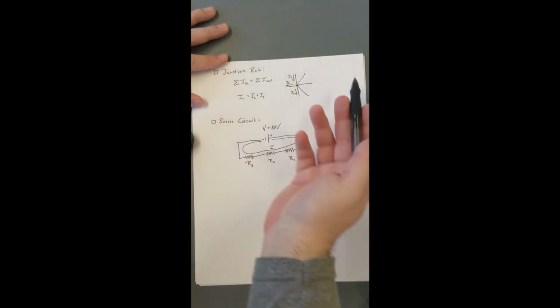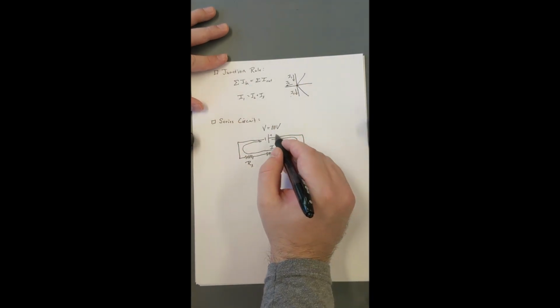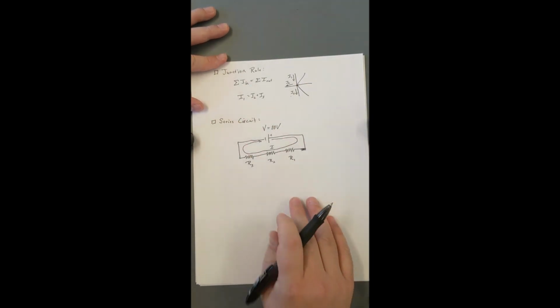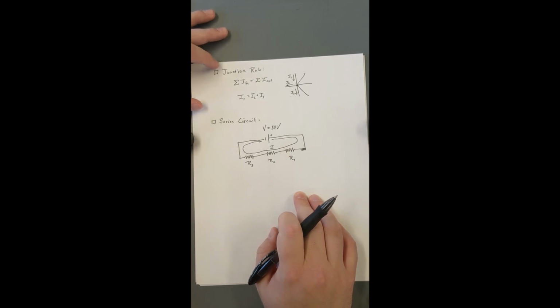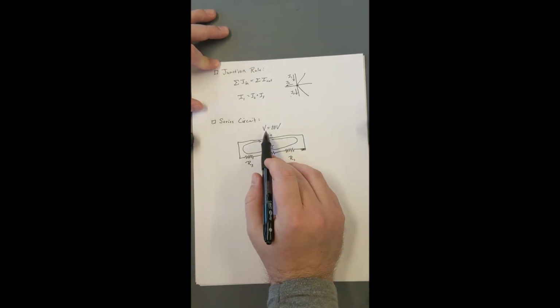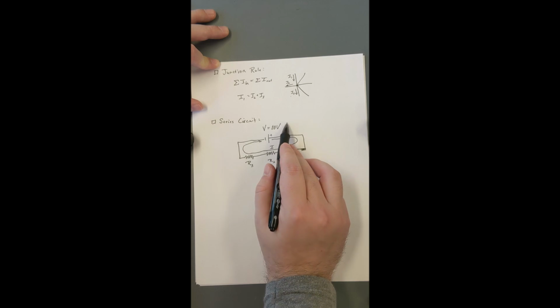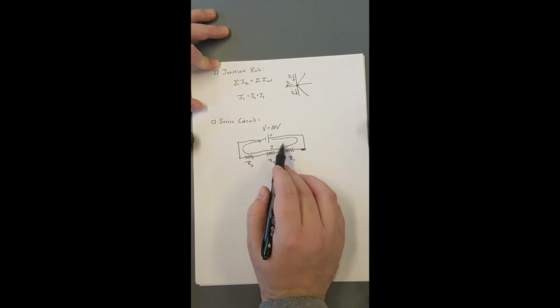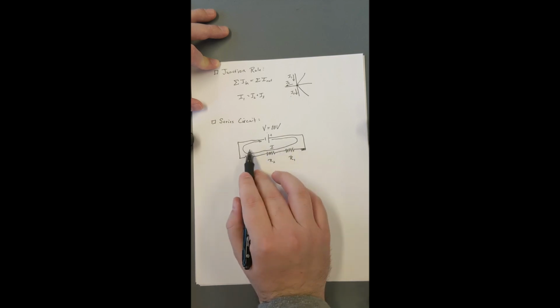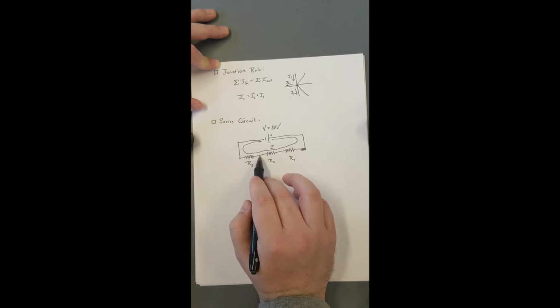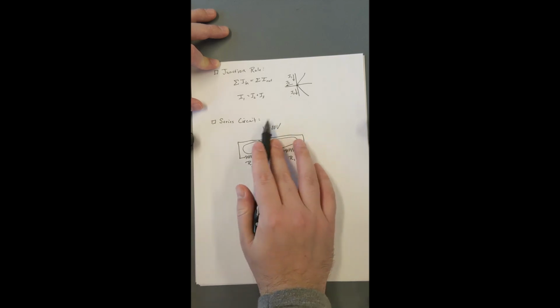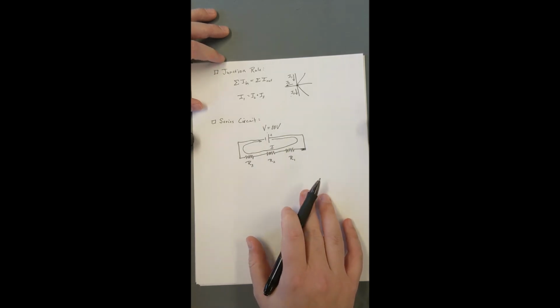All right. We can also apply Kirchhoff's rule, the loop rule, and define this as just one loop. So what we would then expect to see is that the total voltage being supplied to the 3 resistors in total should be the same. So if we add up the individual voltages across these resistors, we hope to get approximately the same amount here.